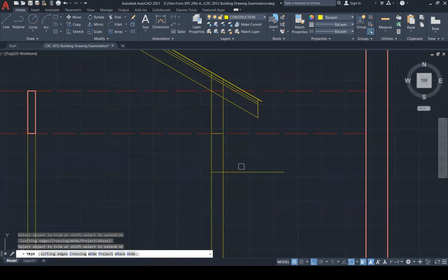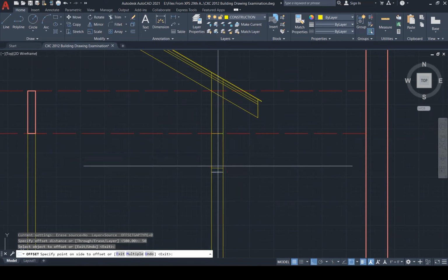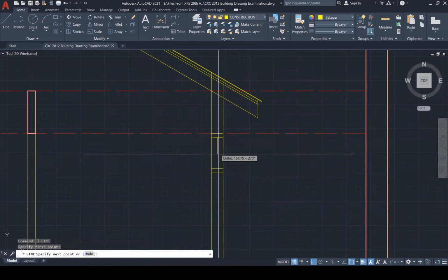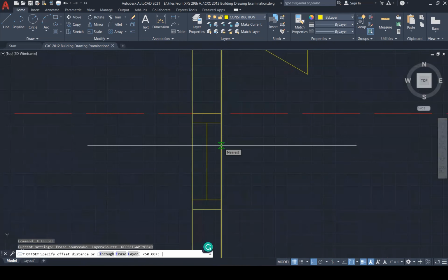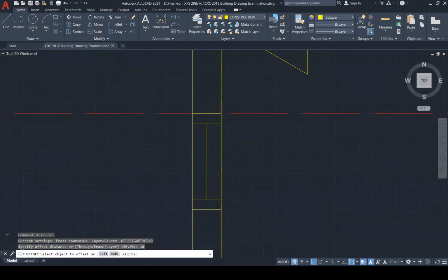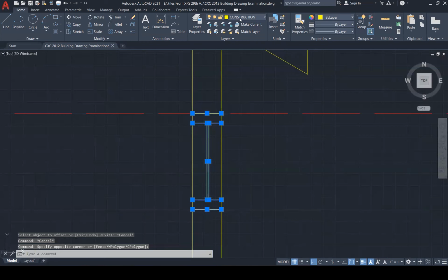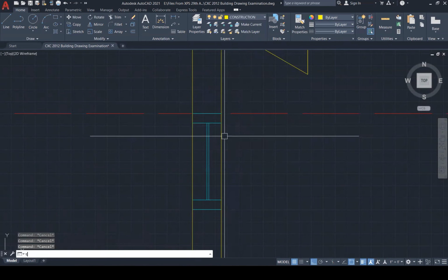I'm going to place a frame of 50 inside, and show the glass panel. Offset the glass panel probably about 10. Yeah, grab this whole thing and place it into the window and door layer.